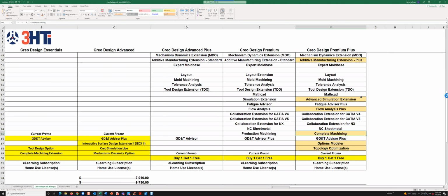So ultimately, what GD&T Advisor does, if you are somewhat lacking on the fundamentals, I'm not saying completely lacking, is it will basically guide you through how to properly put those on the part. So later on downstream, those particular dimensions will work when it goes through a CMM or scanner or whatever it would be to be measured. So anyway, there's a big push. I think when you have model-based definition, it's starting to become a bigger push. And what's been going on for a long time is everything should be based off of the model. So hopefully that helps, Rob.